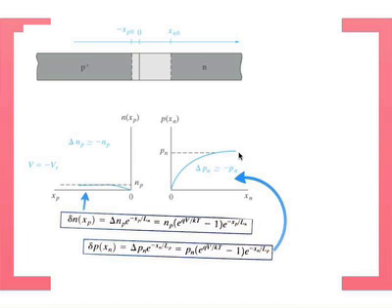So you have a diffusion of holes which come from far away from the junction towards the junction, which is the opposite of what we saw before. And remember, this diffusion is now in the n-type material. It's a minority carrier diffusion that's happening. So the current is now in the opposite direction, right? Earlier, remember, the holes were excess carriers here, and they were going down like this. Now it's the opposite direction. The diffusion is in the opposite direction as well. Current is in the opposite direction as well because it's reverse bias. Okay, so everything again is consistent with the picture you had.